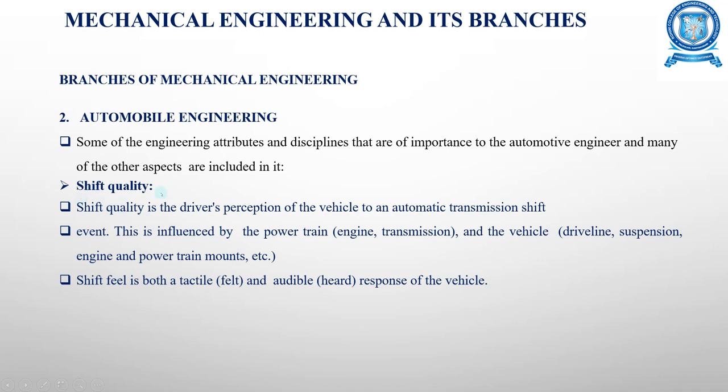And next is shift quality. That is also an engineering attribute and discipline in automobile engineering. This is the driver's perception of the vehicle's response to an automatic transmission shift event. It is normally influenced by the powertrain, that is the engine and transmission, and the vehicle, that is driveline, suspension, engine, and powertrain mounts, etc. The shift feel is both a tactile and audible response of the vehicle.